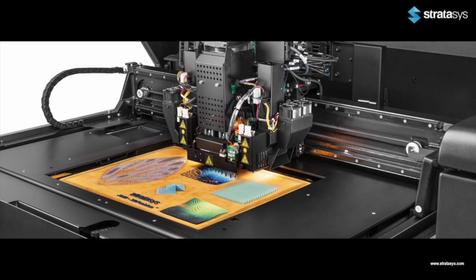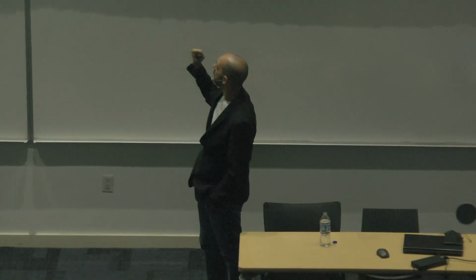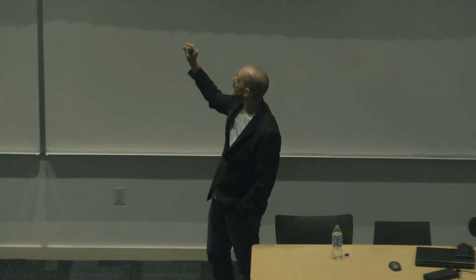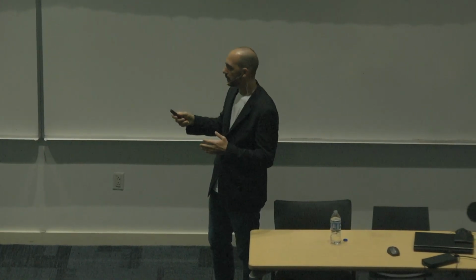And the interesting thing is that you can print some patterns with different colors, different consistency. You can play with flexible material, more rigid material, transparency, different colors. But there is usually a specific thing that you have to keep in mind: as you can see from those printed patterns, you tend to print elements that are disconnected from each other, because otherwise your material is not flexible. So in order to allow the flexibility of the material, you have to keep them separated, which looks like the pattern that we just saw in the animation.